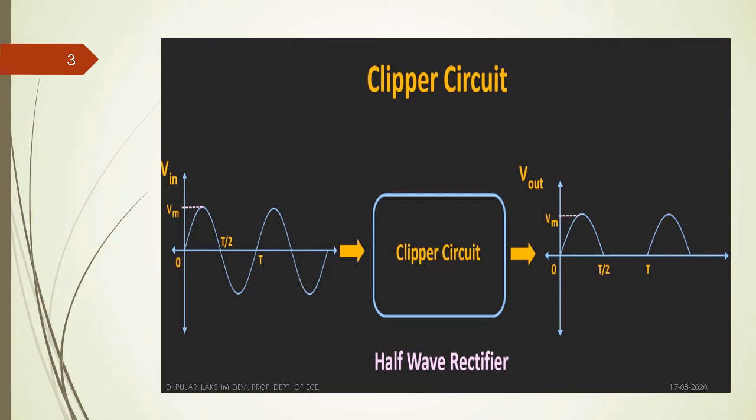That's the reason it's called half wave. Rectifier means that without having the full waveform, half of the waveform is repeated, and a rectifier converts AC to pulsated DC. This is not exactly DC; we still need some filters at the output of half wave rectifiers, which we'll see in the rectifier cases, but here we are observing the clipper functionality with the use of diodes.